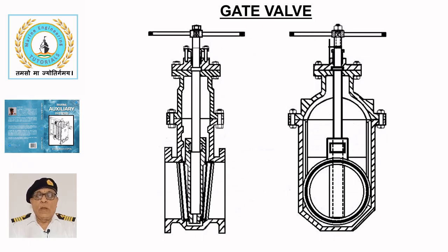Gate valve. A gate valve should be either fully open or fully closed and is not suitable for controlling flow, as the void drawing action of the fluid can cause erosion of the valve seat and gate. When opened, it provides a clear, uninterrupted, full bore straight passage for the liquid as the valve gate is raised. This design offers the least resistance to liquid flow and is therefore preferred as a suction valve in large centrifugal pumps.